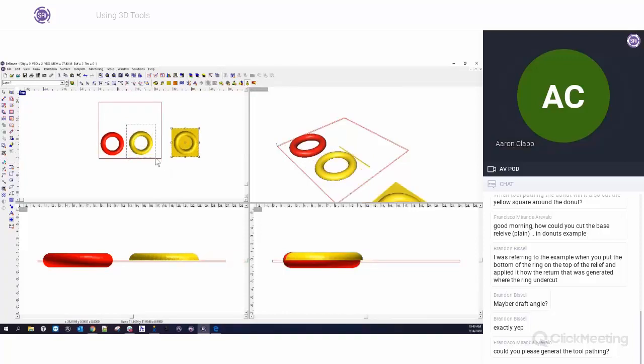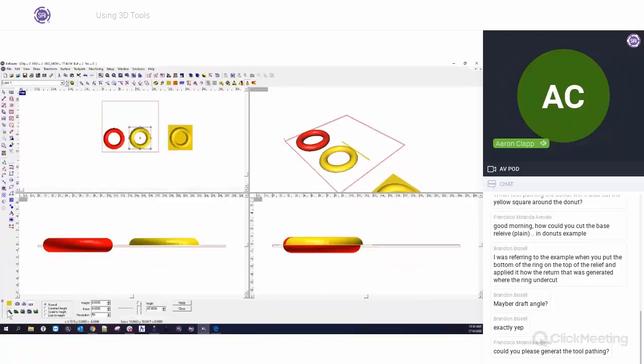So now I can take this shape and I can set it differently inside of the relief. For example, if I wanted to add a little bit of a return to the bottom of this, I could add it via adding a relief. So I could create a relief and just say add to relief and then add a base height to it. I could also do that to the bottom of the relief when I created this flat no thickness. So instead of a flat no thickness, I could say go ahead and add a base to it. That'll help smooth it out.